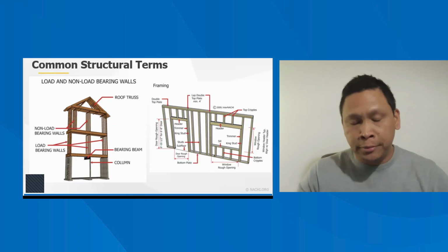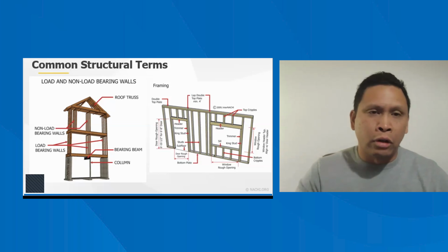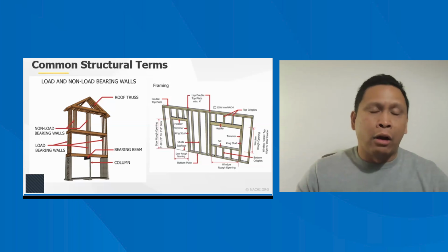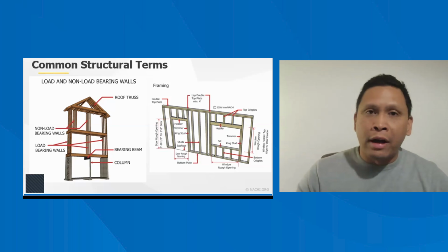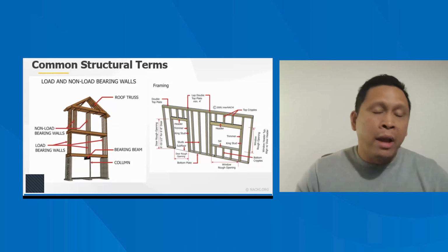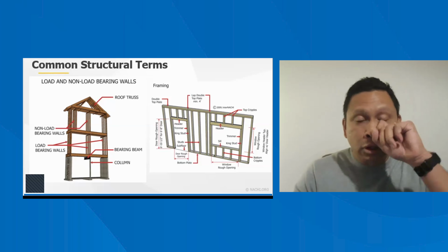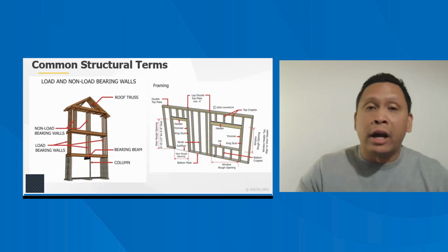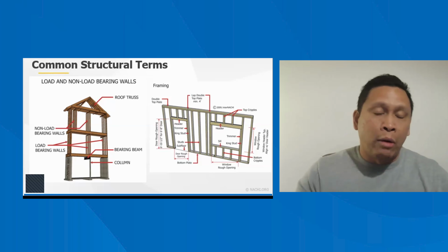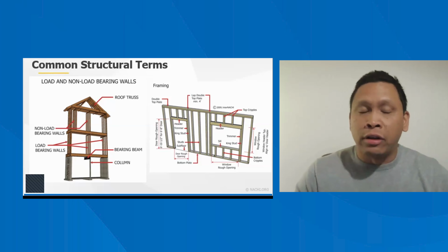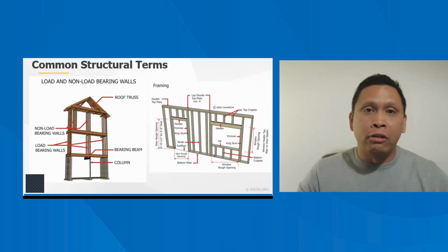So, for example, and we'll also go into more depth about this later, when we see, let's say, a crack on the foundation itself that's maybe a little bit more than a quarter of an inch in width, we note it in the report, right? But we may not think anything else of it until we actually get into the home. Let's say it's in the front left corner of the home in a dining room. And so now we're inside the home. We've possibly forgotten that crack is actually there, and then we're just going through the dining room.